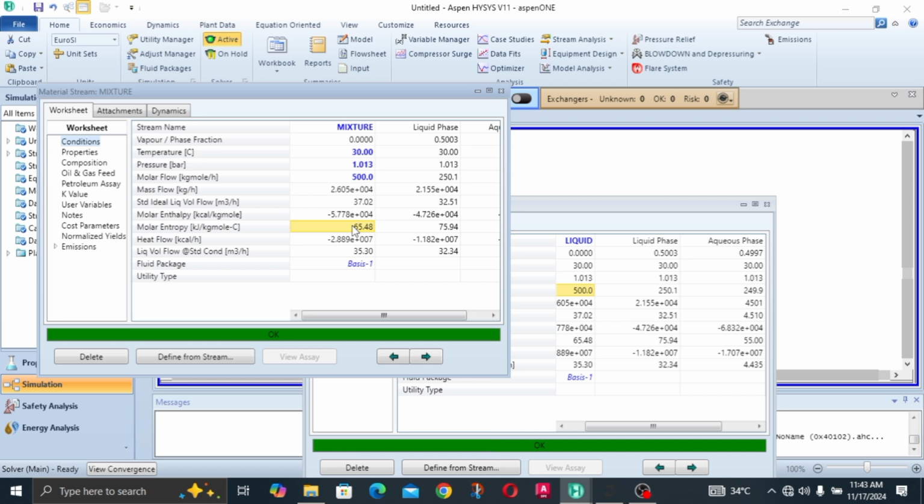Remember, the separator banks on factors such as density and phases to actually separate the mixture into distinct components. In our case, our components are H2O and hexane. But then they are all in the same phase. So how do you separate them when they're all in the same phase? The separator wouldn't be able to separate them because it can't bank on the factor of phase. So the separation wouldn't really work. As long as they're in the same phase, they're all just going to follow one path, and they all go out without any separation.